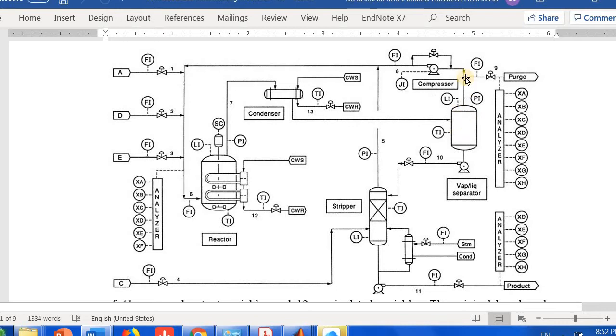Then you're going to have the liquid getting in here, and then the separation process. The separation process happens. Do you want to control the temperature here? Okay, and then the liquid goes in here to the stripper. There's also some kind of level indicator which indicates that level control here is important. And do I want to control the level here depending on how much reboiling I have, or does it have nothing to do with this? I'm going to control the level with the output flow rate.